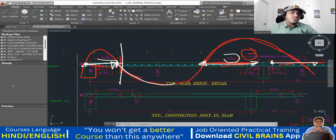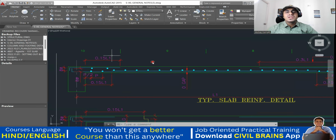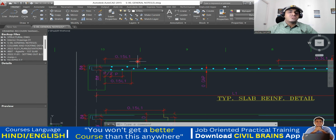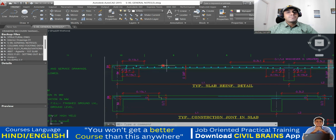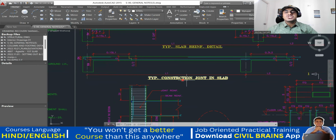So why is it 0.15 only? Why is it not 0.20? Again, people have seen through experience, they might have done the measurements, and a lot of studies might have been done. And finally they found, okay, we'll go with 0.15. You can take 0.16 also, nothing will happen. But you shouldn't come below this. Even if you go beyond this, no problem. Got it? Now coming to the last portion, typical construction joint.